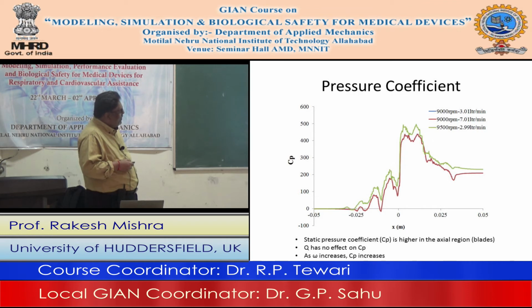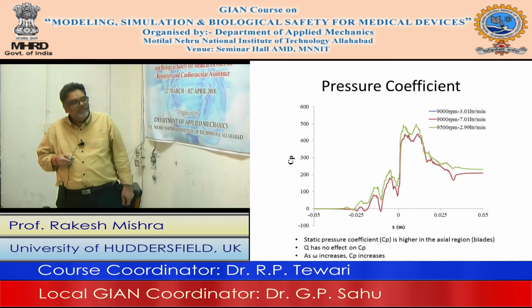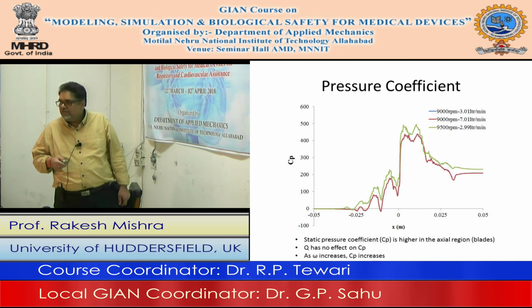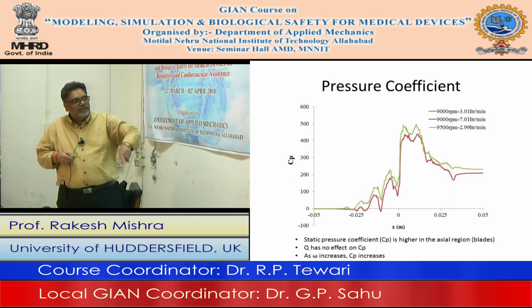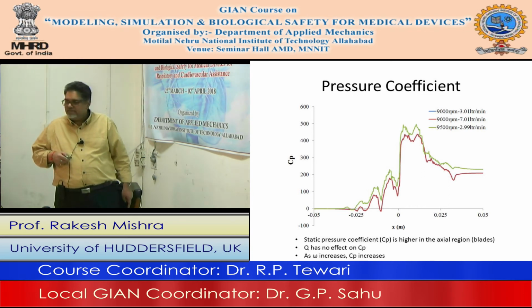And then we have a diffuser part. So in the diffuser part, what is happening? Pressure, sorry, this is at the end of the impeller, then it is going down and becoming constant at that particular point. So this is the impeller geometry here. And you can see how the impeller geometry is affecting the pressure rise. It goes to maximum pressure up to here, and then it becomes stable at this particular point. So the total pressure rise is this minus this. This is the final pressure, this is the initial pressure, and this difference is the pressure rise by the impeller.